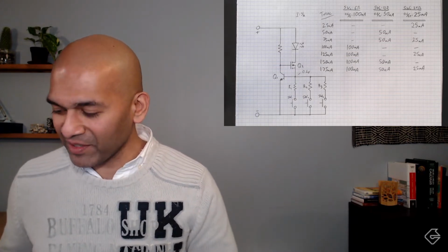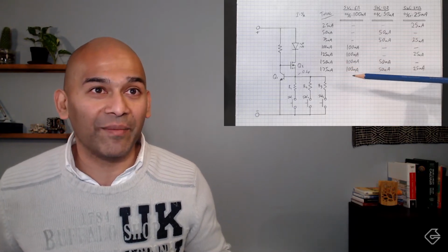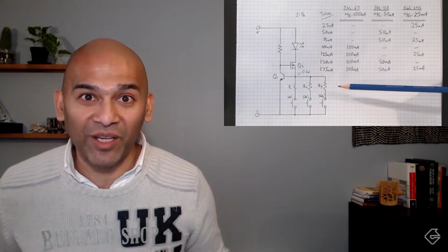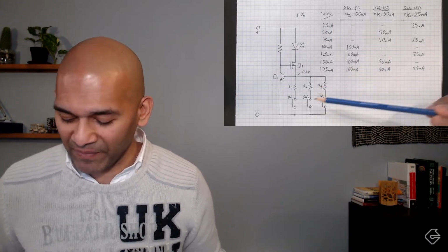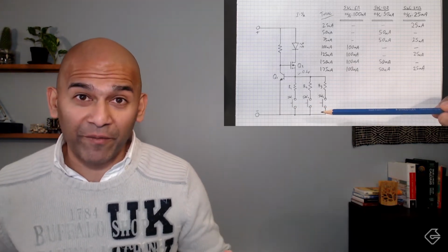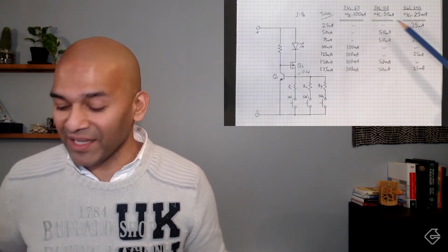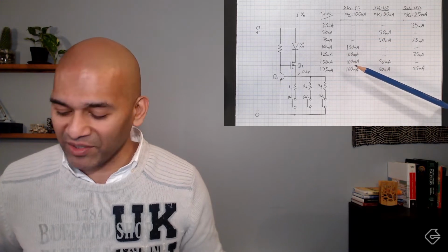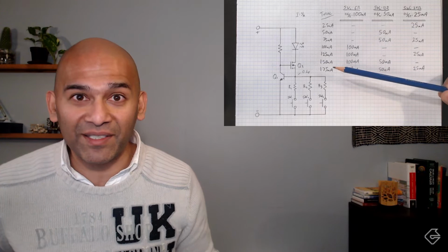And if you remember the things we talked about, what we wanted to do was, just like that water slide example, give our circuit a number of different paths that it can go down. In this design, we had 3 different paths to go down. And we had these switches that will enable us to turn the path on and off. And if you remember, different combinations of the switches will give us different total currents. So for 3 switches, we had 8 combinations, which is really efficient. And it gives us 8 different intensity levels that we can work with.